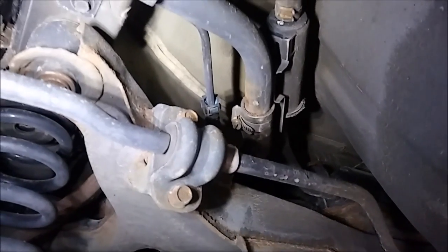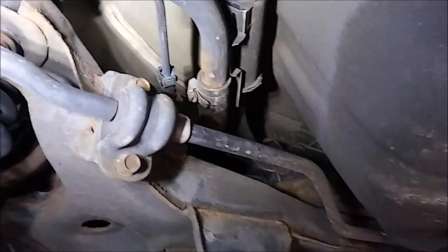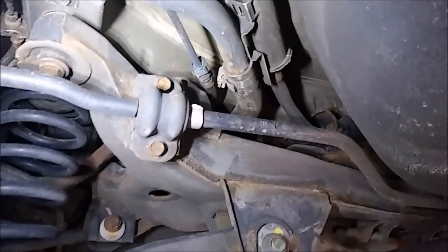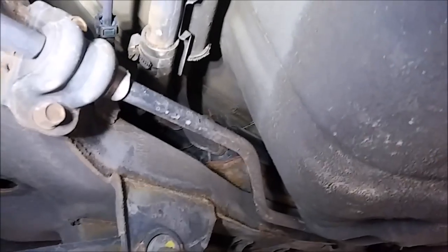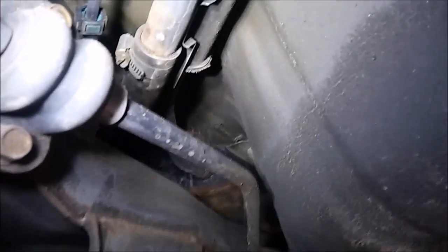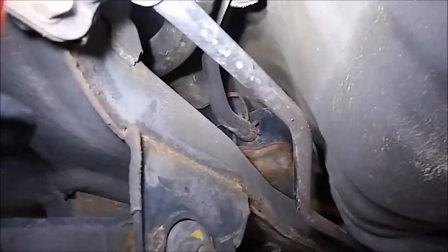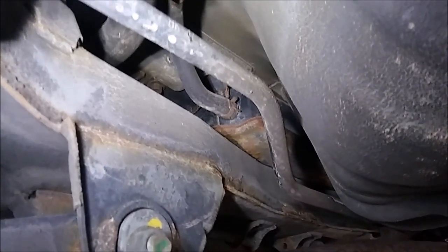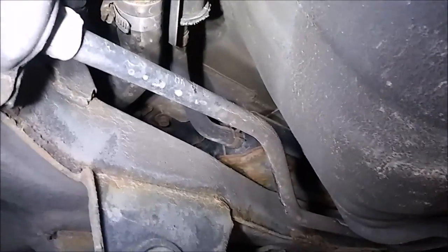Alright guys, so my hopes with this test are I want to manually energize this purge solenoid and pull this tank into a vacuum myself, and then evaluate what sort of leak we're dealing with. Right now I've got the vehicle lifted up. As you can see right here above this rear subframe area, that's going to be the canister. What I'm looking for is the canister vent solenoid.